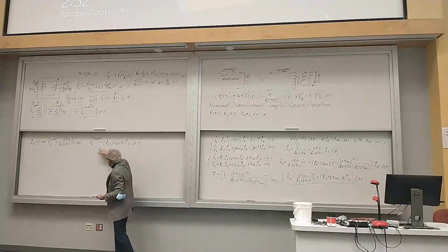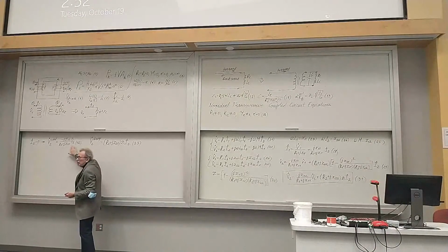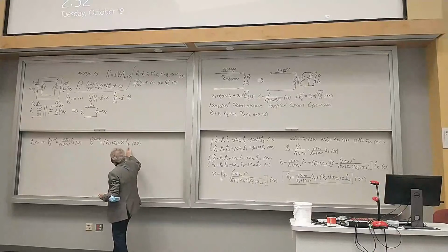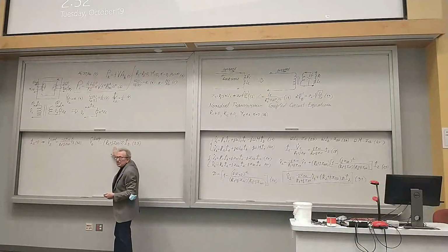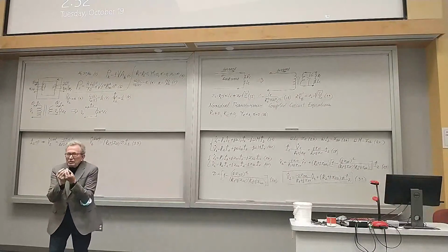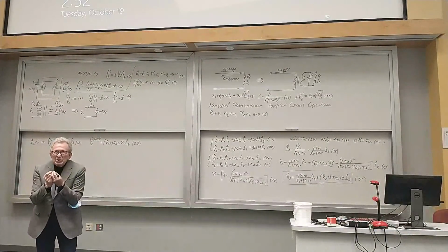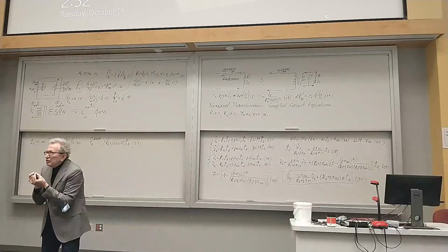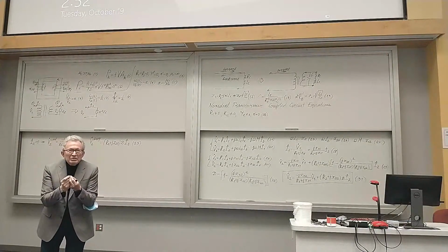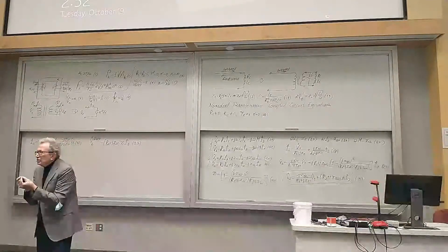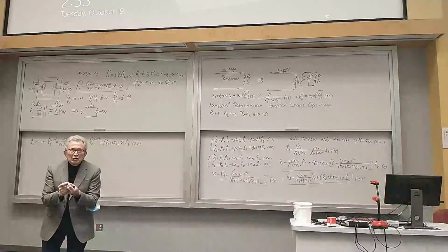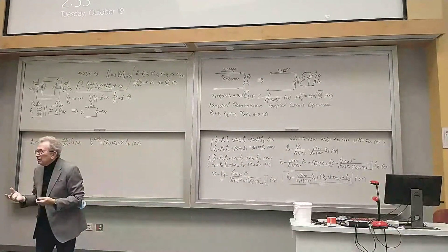And the change of the voltage, this term will not change. It's constant. The change of the voltage is due to this term, due to the drop of the load. And for the transformer to be a very good transformer, to satisfy this condition, that we can provide the power to our customers with more or less constant value of the voltage in the face of continuously predictably changing load, this term should be small.